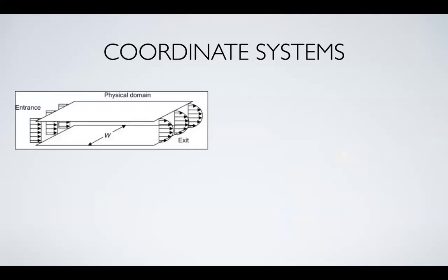For example, if I have a parallel plate like this, and we have a flow through these parallel plates, what kind of coordinate system are you going to choose for this system? Cartesian, of course, right? Why not cylindrical or spherical? Because the surfaces are flat, they are perpendicular to each other, and it's going to be the simplest one. If you did cylindrical, for example, it would be very complicated, right? So in this case, you can set up Cartesian coordinates for this system.